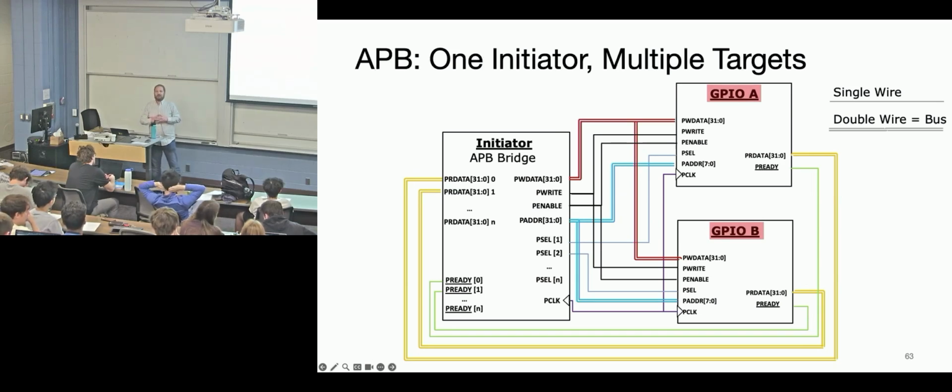So a bunch of electrical engineers got real worried that if you were clocking in your data, or data was changing when you're clocking in, and there's an edge condition, if you look at all the circuits, the circuit can literally get jammed between a 0 and a 1. They're like, oh no, if that happens, bad things will happen to my circuit. And they're like, how often does this happen? Not very often. But it still could happen. And so what they did is they said, put 2 D flip-flops out there, and that eliminates the problem.